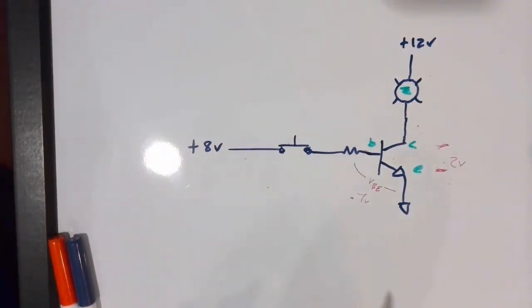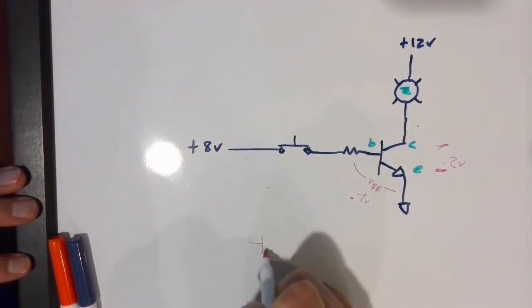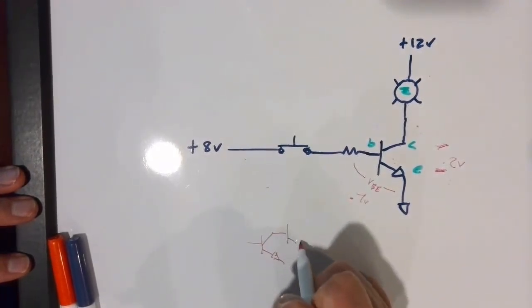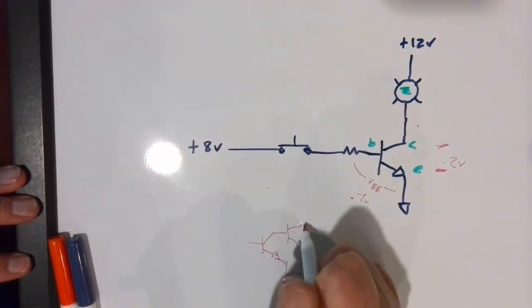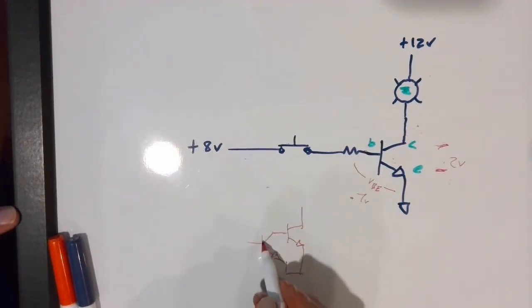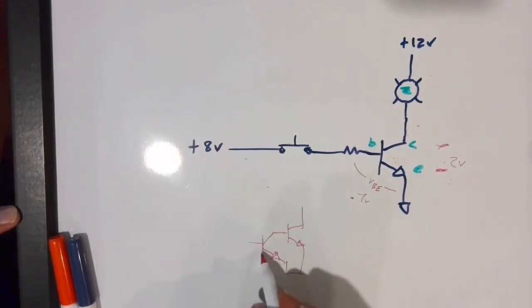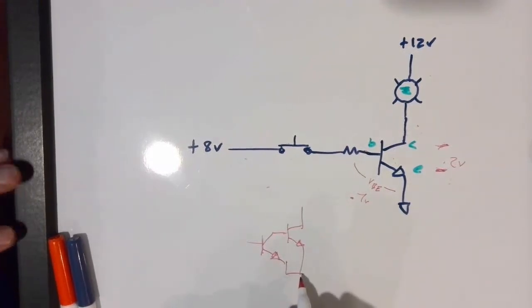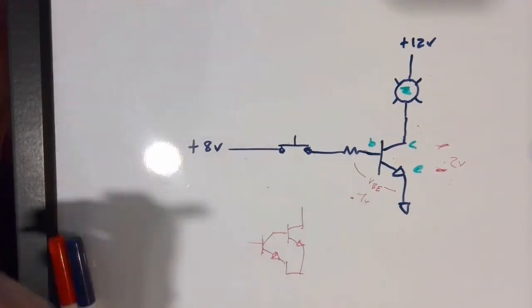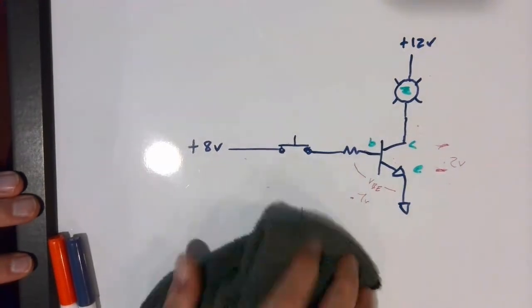What's interesting, in the lab, we're actually using a circuit that uses what is called a Darlington transistor, which essentially connects 2 transistors together like this. Now, you might think, why would you want to do that? What's the advantage? Well, it turns out that the beta or the current gain of each of these transistors is amplified by the other beta, so you get these huge gains on the order of tens or hundreds of thousands. So that's one advantage. But what's interesting, though, is that because of the way that the circuit is arranged, the VBE ends up being a lot larger, so it's more like 1.4 volts.